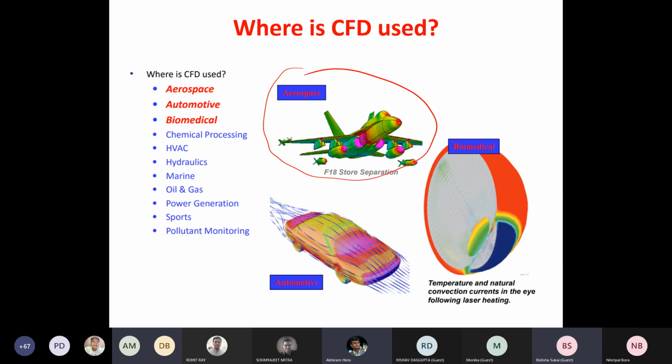All of this comes from the flow factor, I mean flow analysis, how the fluid flows. If you see this schematic diagram, you can do such analysis of fluid flowing past this car, how the streamlines etc. will look, and accordingly you can make some design changes. Even big companies, when they design the headlight of a car, what the shape of the headlight should be and what its beam direction should be, that can also be done through CFD analysis. So in car design and car manufacturing, a lot of CFD can be applied.